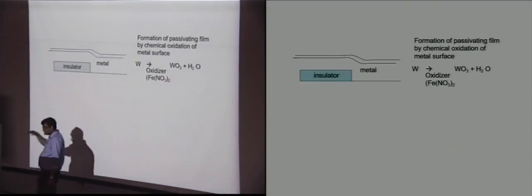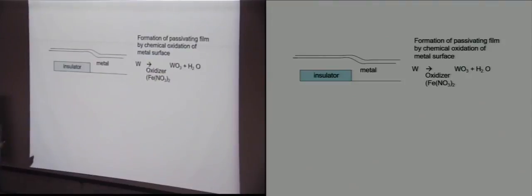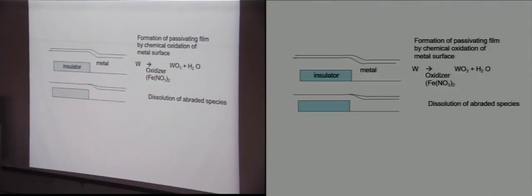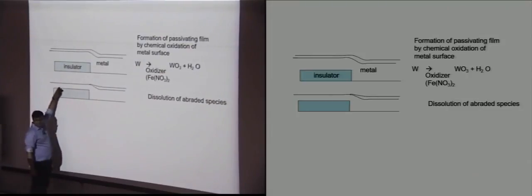Now when you are polishing it, the polishing pad will touch this part more preferentially over this part, right, because this part is sticking out. Therefore, when it starts to rub off, it will remove the tungsten oxide over here. The moment the tungsten oxide is removed over here, the other etching components of the slurry will start to attack over here.